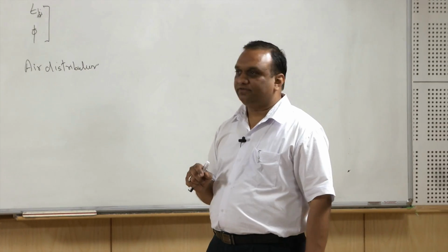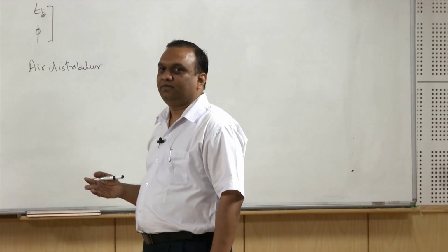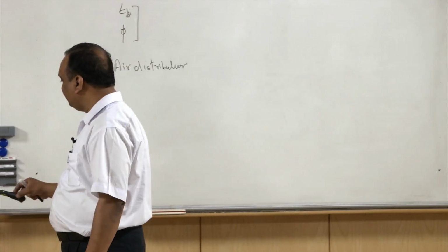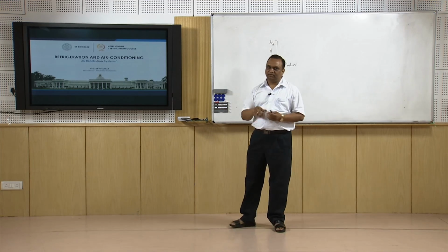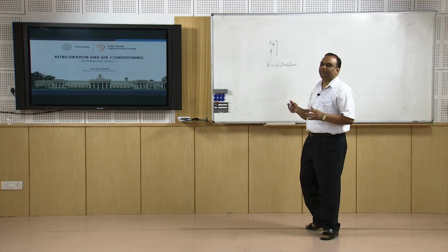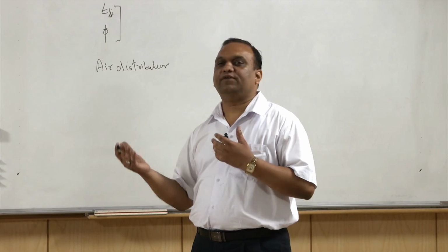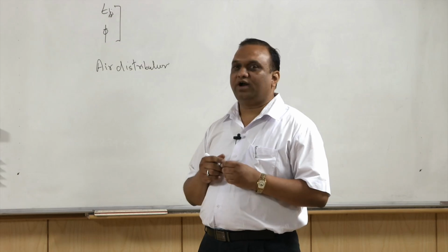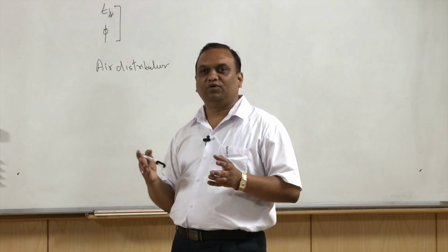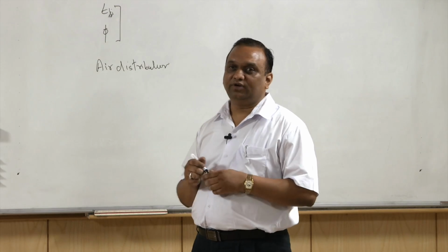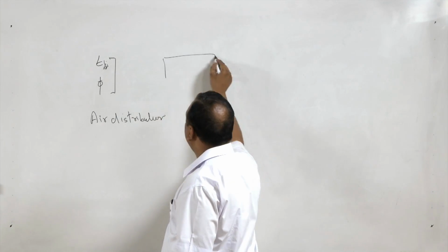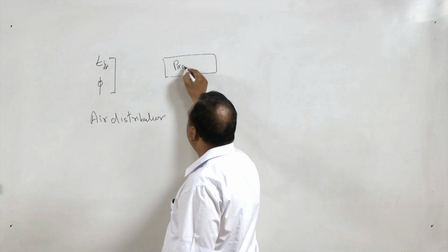For small capacity systems like direct expansion package type units, there are different types of air conditioning units. Normally we use split AC or window type AC. But if the cooling load in a building is, let us say, 5 or 6 kilowatt, it is not recommended that you go for multiple units of window type AC. Instead, a package type of system is recommended.